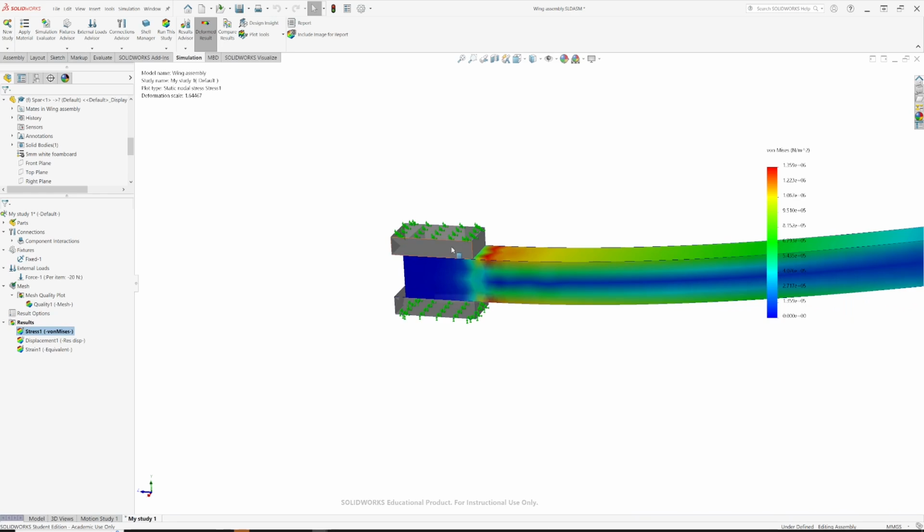However, in practice, you are actually gripping it, so the thing is going to be stressed slightly because you're squeezing it. And what goes on in here can be a little bit complicated, but overall, you would expect this thing to fail just outside the vise.